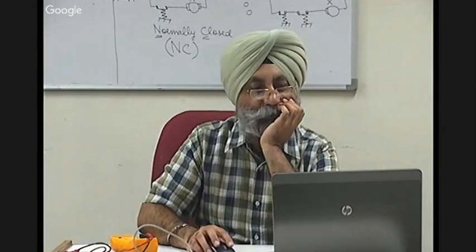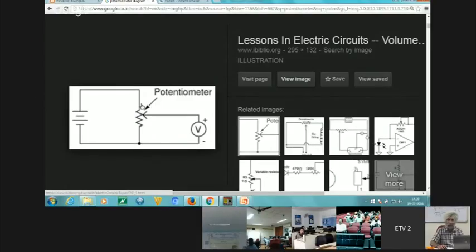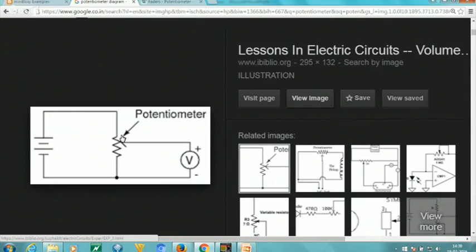So that is a potentiometer, right? It's a very simple device, yet it is omnipresent. The fan regulators, they are potentiometers essentially. So in a potentiometer, we have a resistance to which we supply a fixed voltage. If the resistance is say capital R and the voltage is say capital V, then the current in the circuit will be how much? V by R, right?